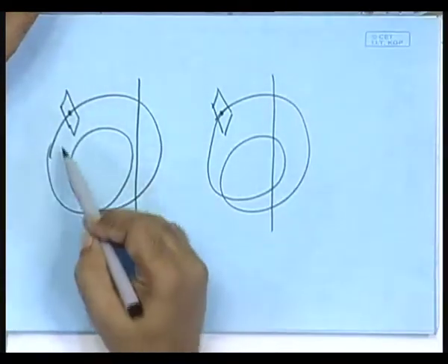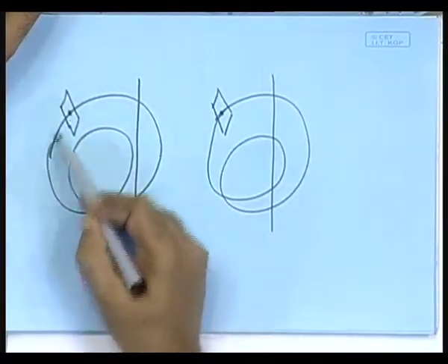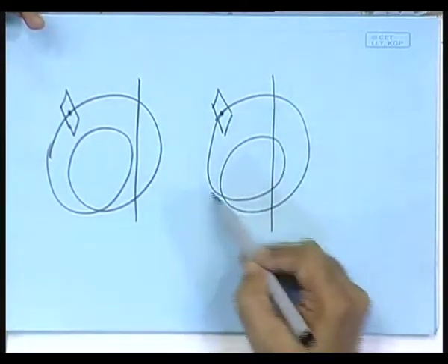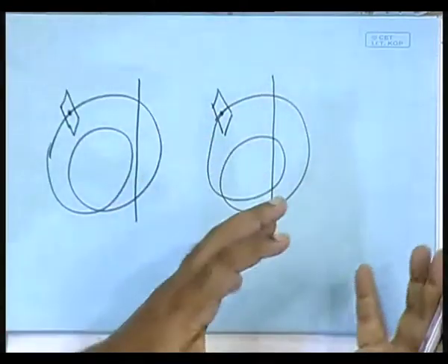So, in one case you will have to obtain the eigenvalues of this orbit, its Floquet multipliers, and here in this orbit, and these two Jacobian matrices will need to be substituted in the theory that we already presented, and there the theory will predict the outcome of this bifurcation. This is how we apply the theory to a particular concrete situation of a non-smooth dynamical system. Is that clear? Okay, fine.